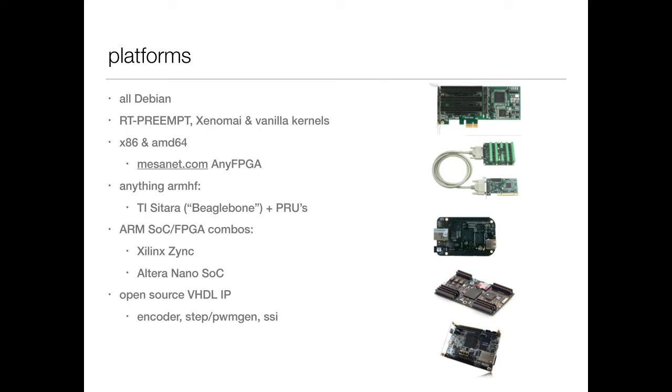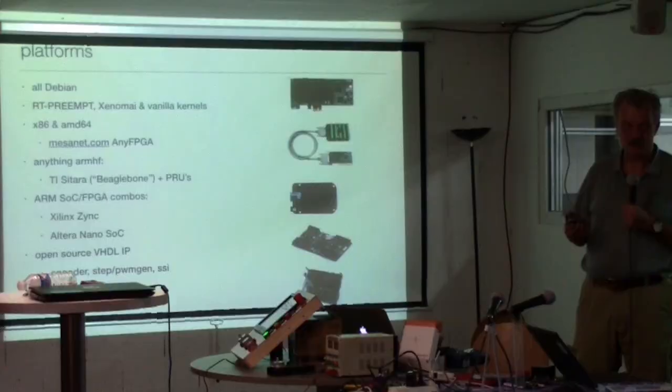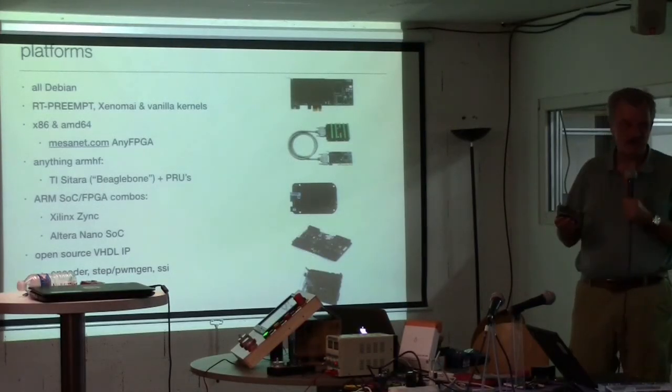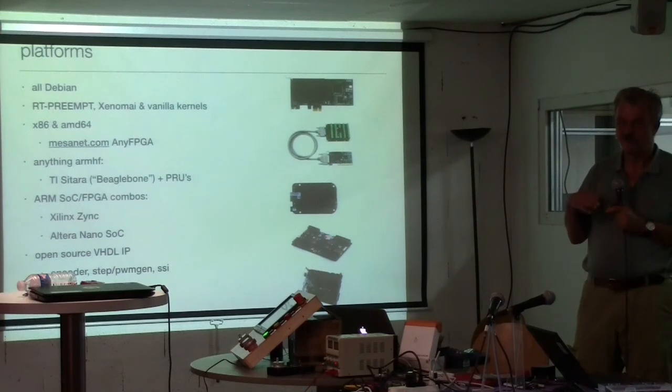Now, many of these platforms already have I/O devices, GPIO pins, various buses you can connect to. But in embedded devices, these I/O pins are typically connected to a ball of the die directly. So they have very poor I/O isolation, no level isolation.